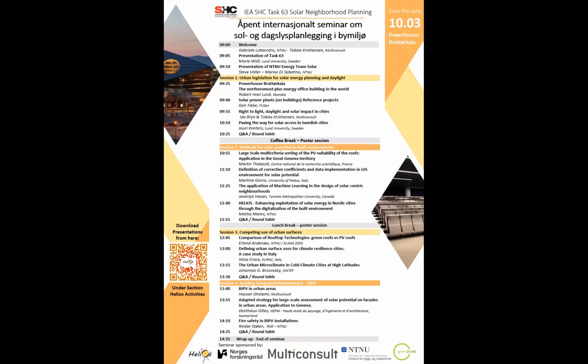Yeah, I don't have. I will test these panels further in the cone calorimeter, etc. But based on what I saw, it's basically just a thin polymer film. It does not contain a lot of combustible material. It's just maybe 1 millimeter or something like that. So it's not really a large heat load, but when this combustible material burns in this small cavity, it generates enough heat to maintain a high temperature in that small cavity, and that makes the fire propagate.